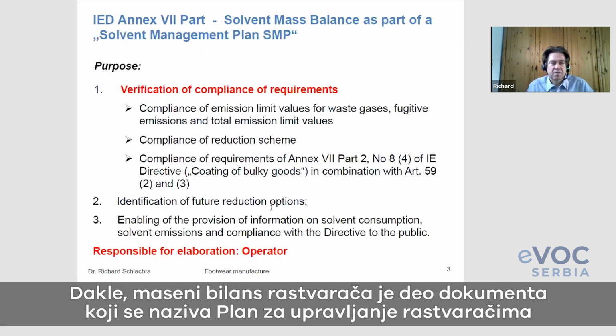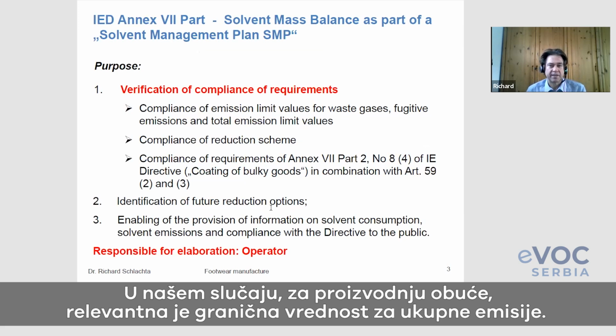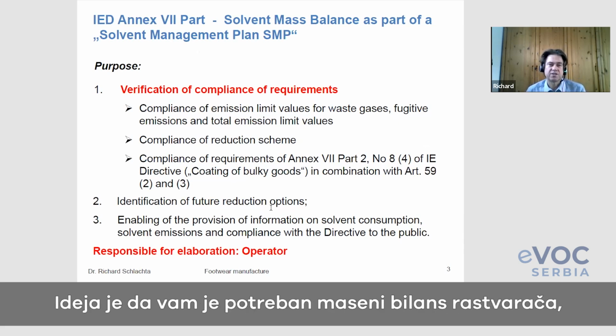So the solvent mass balance is a part of the solvent management plan, and the idea is to verify the compliance. And in our case, for the footwear manufacturing, the total emission limit value is relevant. So that's the idea. We need the solvent mass balance. It's like a measurement report.